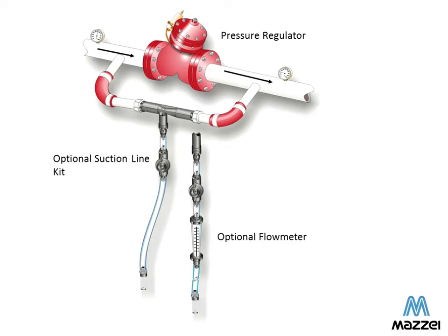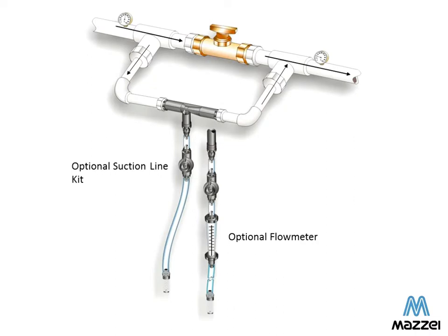So this is an automated type of system where you have an automatic pressure regulator in place. This could also be done manually. You could have a manual valve here. It serves the same function. You just close that valve down until you initiate suction. Remember, suction is initiated when you have sufficient pressure differential between the inlet and outlet of the injector.